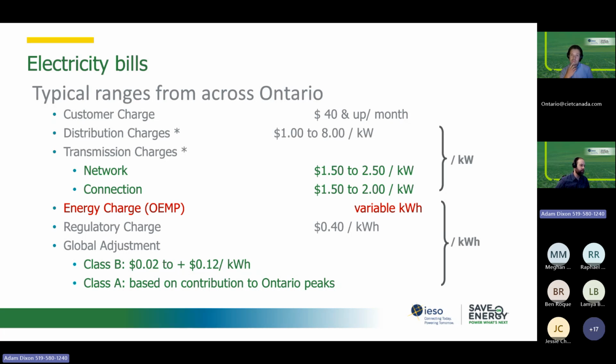So your demand charges may be a bit less than somebody who's connected to both. Then you have your kilowatts. That's how fast you're using power, and you need to be charged for that in order to account for everybody turning on all their stuff all at once. The grid does have to ramp up and bring on more capacity, so you do have to pay for them to increase that capacity. And again, if you're on time of use, that's all built into one. This is what you may see as a bigger customer.